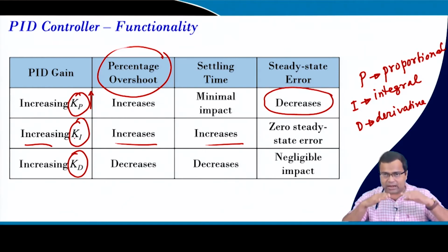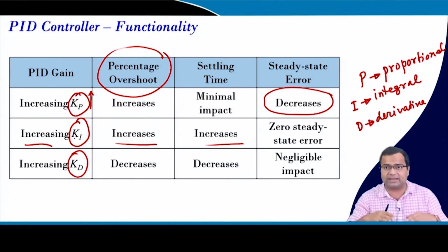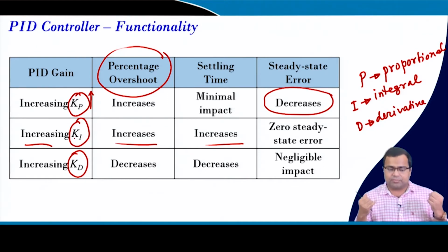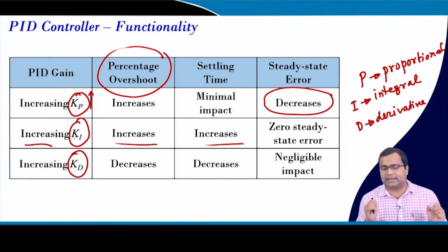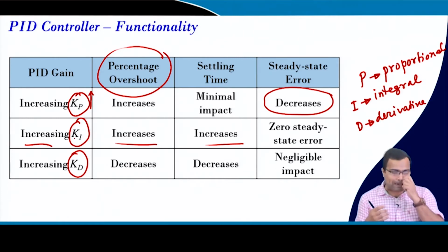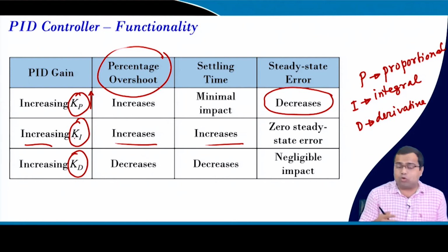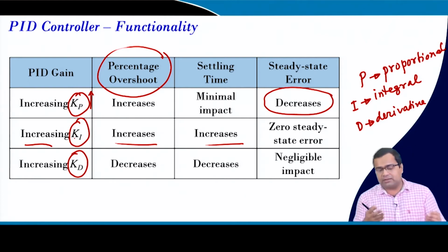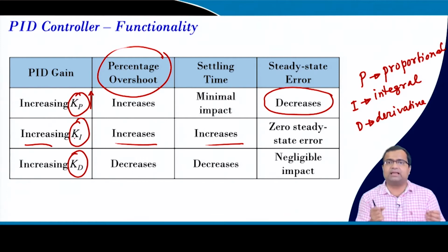That means at lower input voltage we will see a lower loop gain. In order to anticipate that, we need to increase the integral gain, because we need to achieve a certain DC gain, and this higher integral gain can be problematic, because it can cause a poor phase margin.